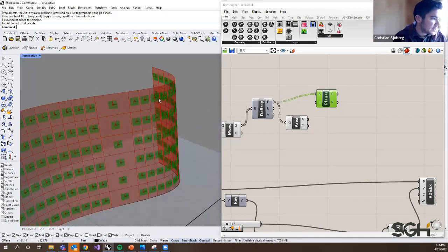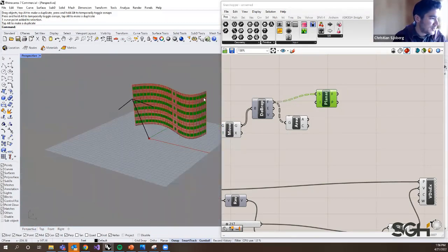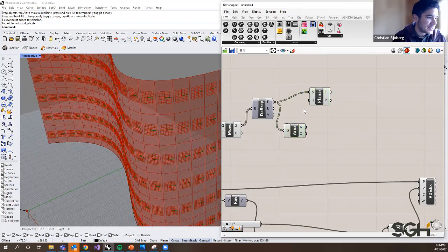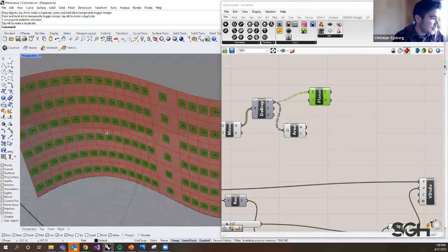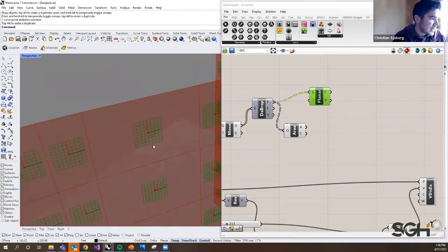All right, so from that you more or less get what, if you're used to making finite element models, you might consider the local plane, right? This is the plane that defines the coordinate system of all the surfaces. So now we need to reflect off this plane. What I'm going to do is extract the z direction of each of these planes.